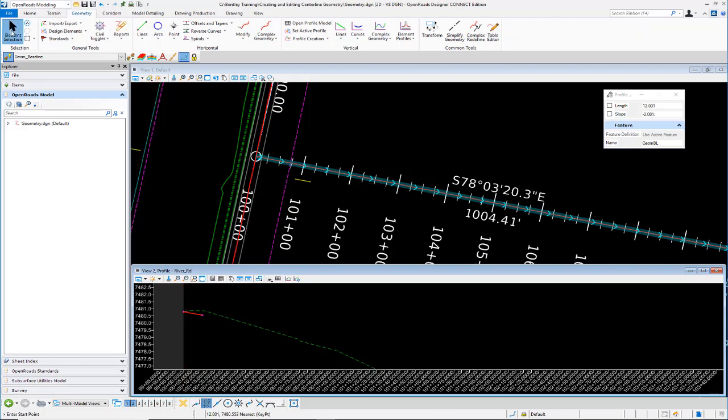I'm going to go to the element selection tool and we'll check the slope and the distance. You can also see some snap icons being displayed, which indicates that we did create a snap rule to those intersecting points. So if the corridor were to move or update, the geometry you just placed would also move and update as well. It's very important to remember that.